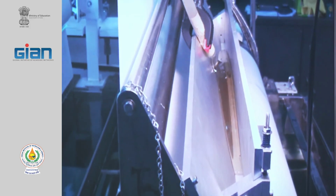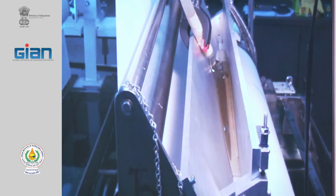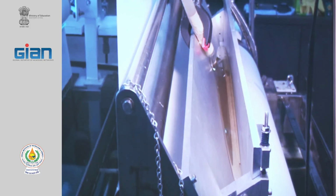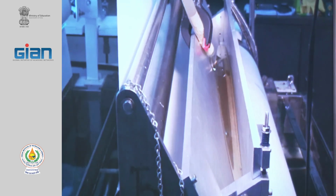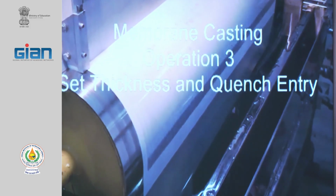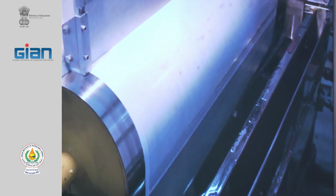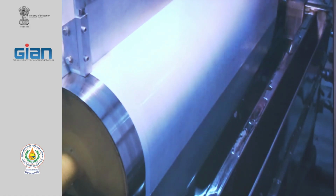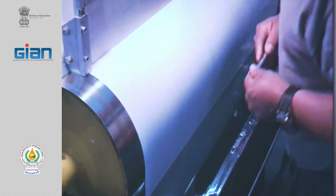You see, we have a polymeric solution like honey. Its viscosity is similar to honey, and also the color. This is the film applicator. We can adjust with this the thickness of the layer, and the fabric begins to go from the bottom of this casting knife, doctor knife, and coat